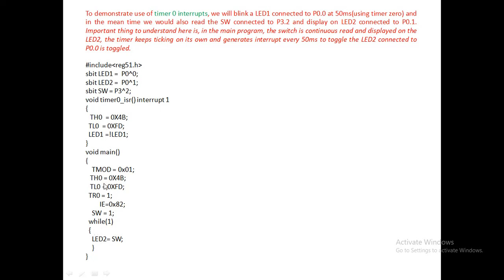What is the beauty of using the timer in interrupt programming? The flag bits are automatically set as well as reset. As a programmer, you have no need to reset the flag bit. Once you run the timer, it is sufficient. You need not make TF0, the overflow bit, 0 after it overflows. The flag bit is automatically cleared.